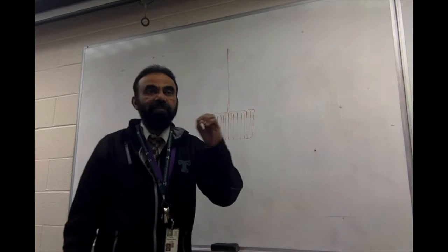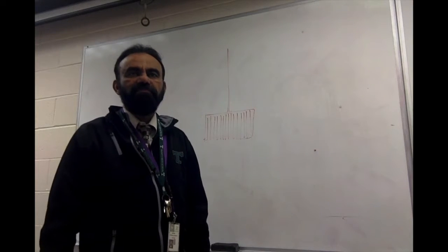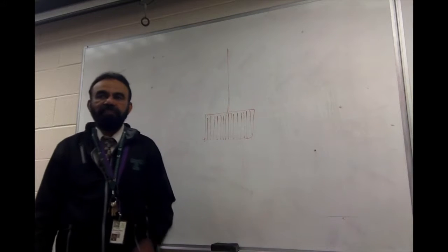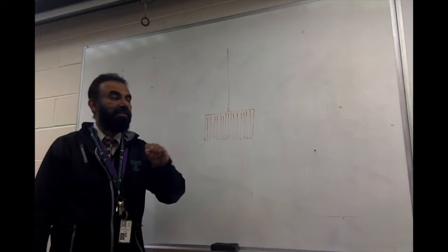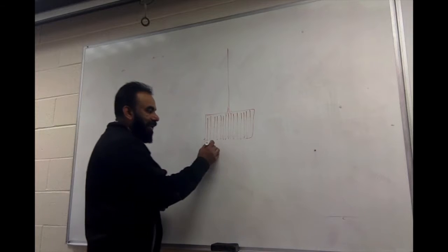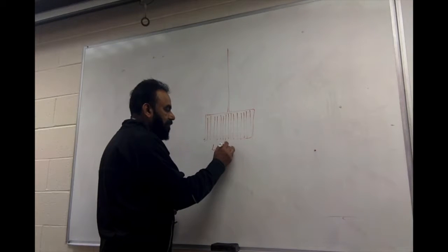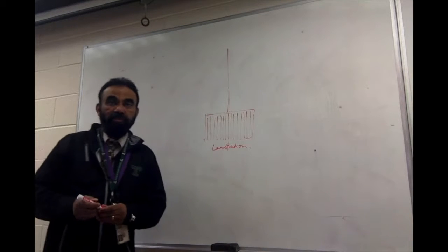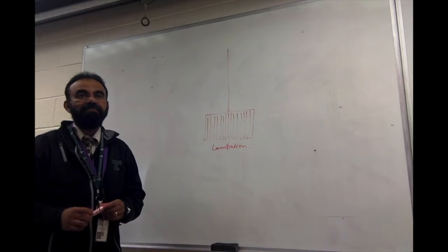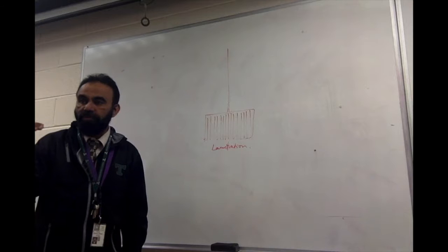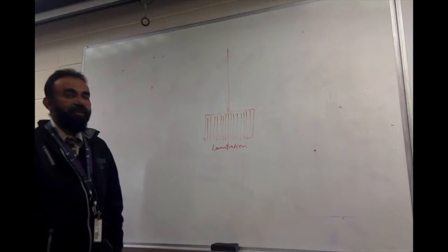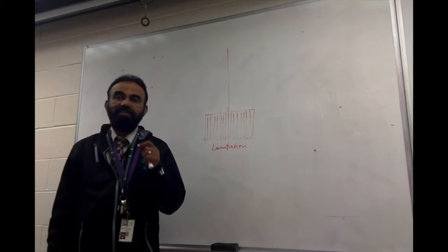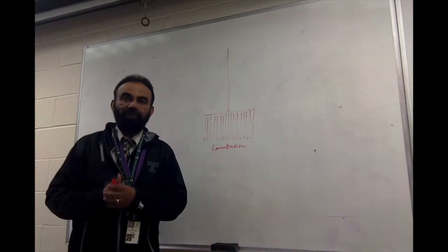You cannot get rid of eddy currents completely. Completely not possible. You can minimize them a lot by using this so-called lamination. By laminating the material, you can get eddy currents minimized to a good extent. That being said, that is one of the losses that you cannot completely avoid.